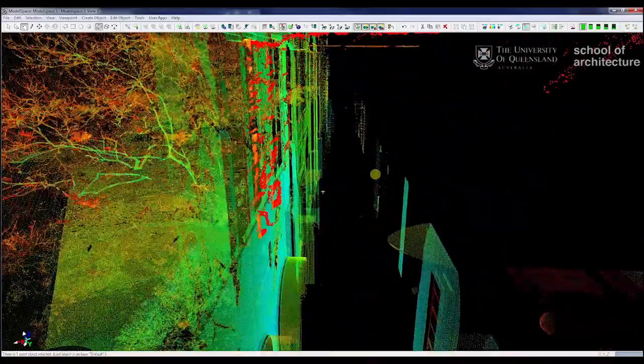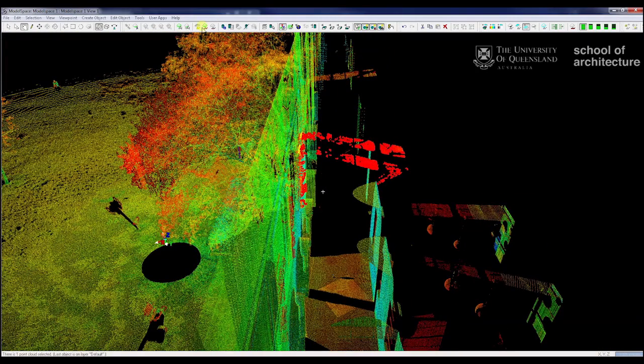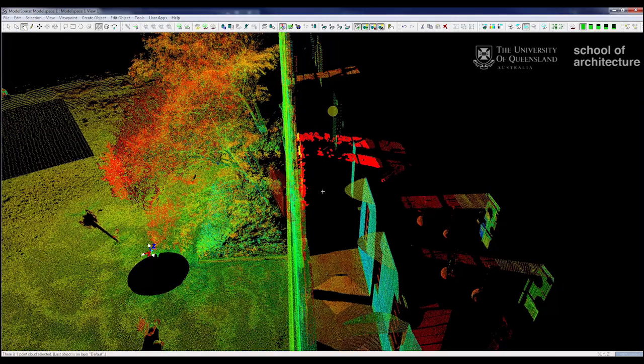Now, one thing to consider as well, if I have captured a little bit of additional data, which is a little bit there, I'm not going to deselect it. You can just use the manual tool again and use remove data inside fence. You see that data has then been removed from the fence, and I can just quickly highlight it again. I'll use my polygon tool once again to go around, add it back in. And it's the same methodology, inside, outside fence, and then just press delete.